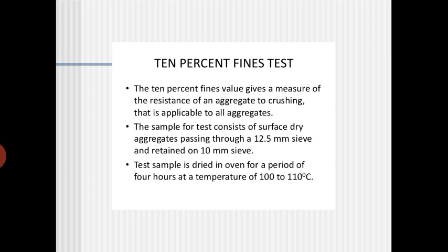When you apply the compressive load on the 3 layers, make sure that 10% fine particles come out with whatever compressive load you are applying. 10% fine means that with that compressive load on the 3 layers, 10% fines should come.